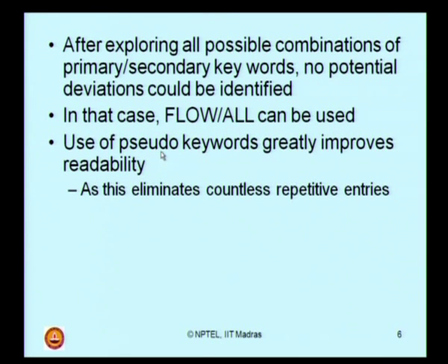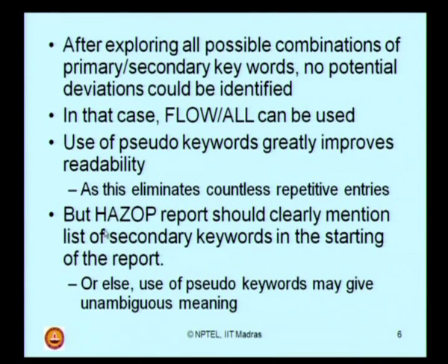So, use of pseudo secondary keywords greatly improves the readability, because this eliminates countless repetitive entries. But a Hazop report should clearly mention the list of secondary keywords in the starting of the report, that is mandatory.